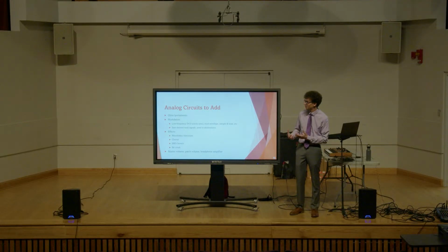So now I'd also like to have some effects at the end of the signal chain, that being wave folding or distortion. Wave folding is really interesting, if you're not familiar, and I wouldn't be surprised if you weren't. Wave folding is an effect where once your input reaches a threshold value, it starts folding on that value, so it inverts at that threshold. So say you have a triangle input that you're going to fold. Once it reaches your upper threshold, it will invert for the rest of its wave, and then it'll come back up and finish its regular triangle.